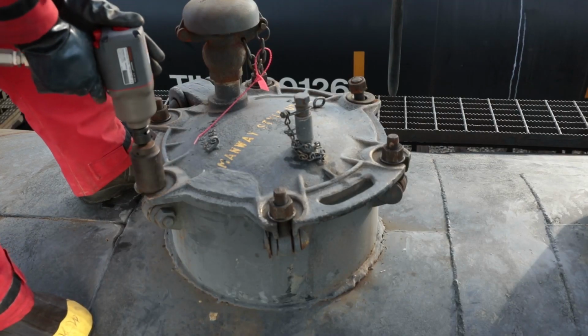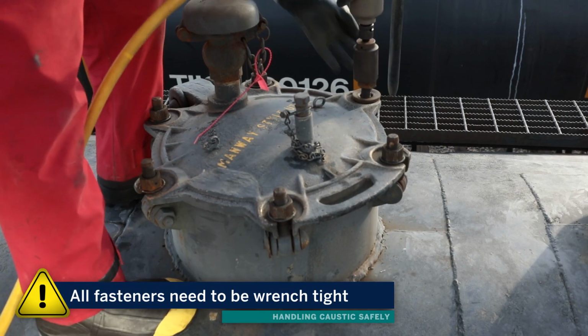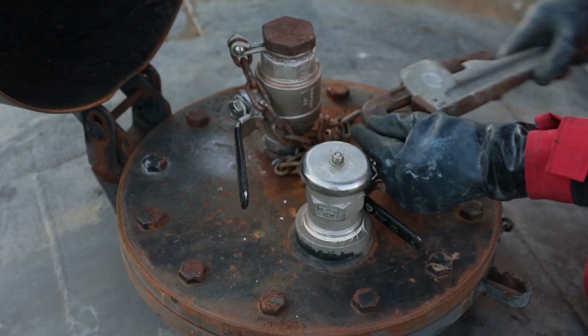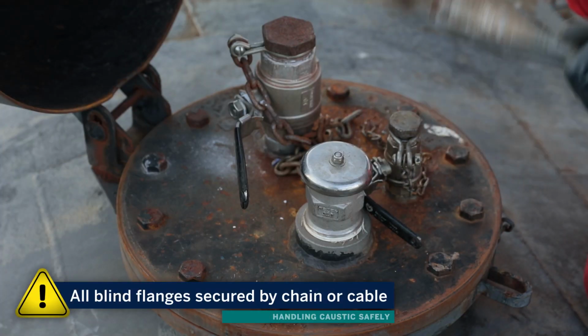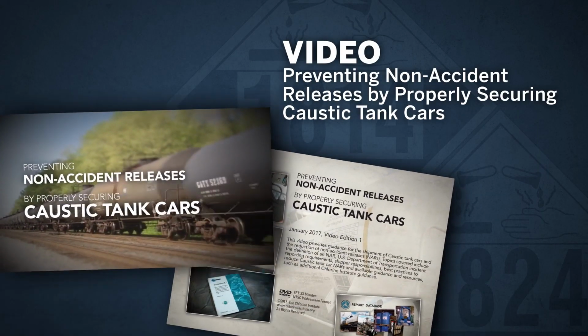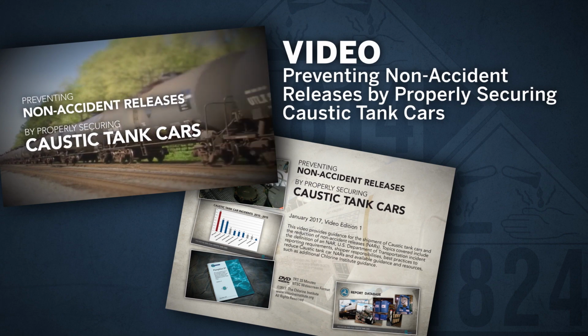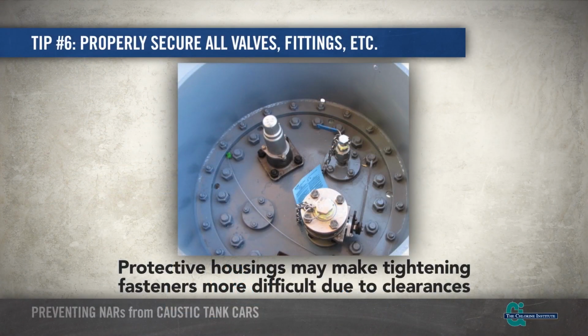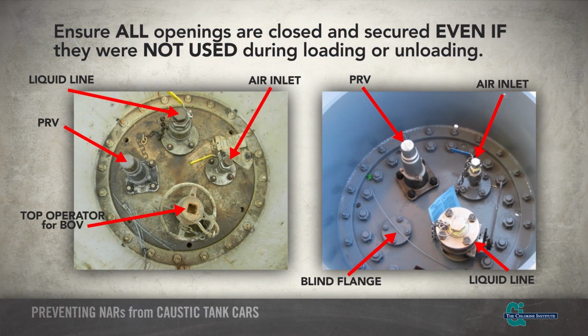A word of warning: DOT regulations and AAR standards require fasteners to be wrench tight and all blind flanges to be secured to the tank car by chain or cable. The Chlorine Institute's video Preventing Non-Accident Releases by Properly Securing Caustic Tank Cars provides details on best practices for properly securing and inspecting the tank car to reduce leaks during transport.